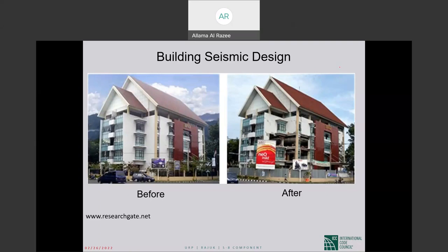So in ordinary design, we design for service loads, loads that most of the time are expected to apply to the building. Under the load, the building gets some deformation, but we expect that after removing the load, everything should return to its initial state, no damage.